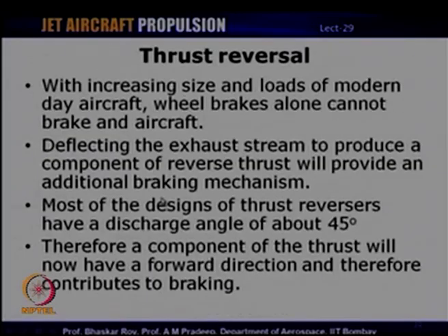Now, the other major function of a nozzle is thrust reversal, and thrust reversal, as I mentioned, is one of the ways of assisting the wheel brakes to decelerate and bring the aircraft to a stop in the shortest possible distance. So, with increasing size and weight of an aircraft, it is becoming more or less impossible to brake the aircraft just using the conventional wheel brakes.